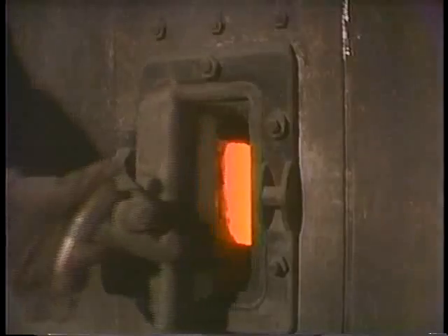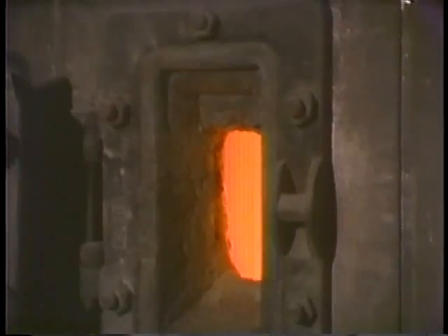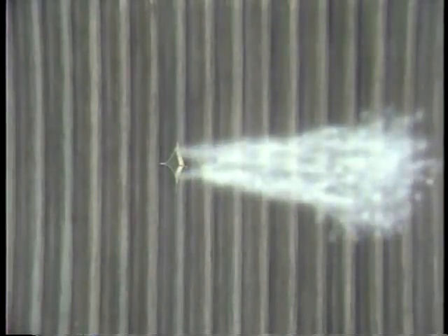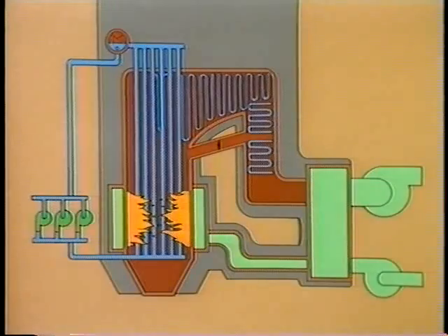Now, there are other situations that can lead to a loss of flame that the operator will not be able to anticipate. A typical example is a boiler tube rupture. Boiler tubes are subjected to both the intense heat of the furnace and the high pressure of the boiler. On occasion, a tube may rupture, blowing water and steam into the furnace, superheater, or economizer section of the boiler. Depending on the location of the rupture, it may endanger the boiler flame.